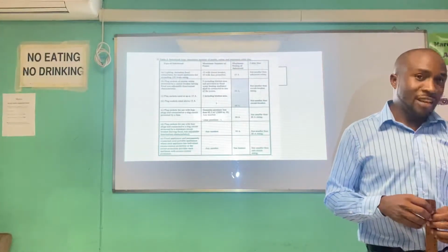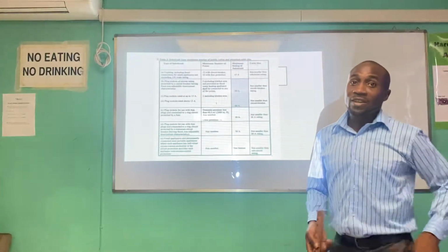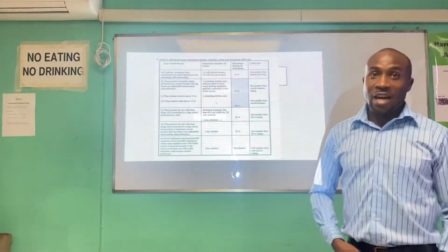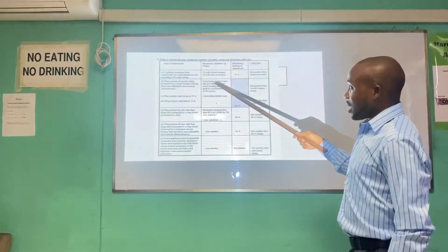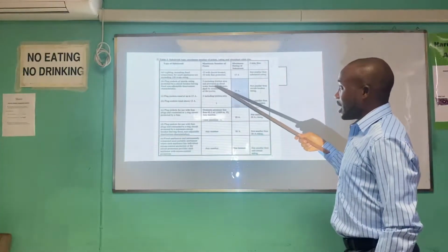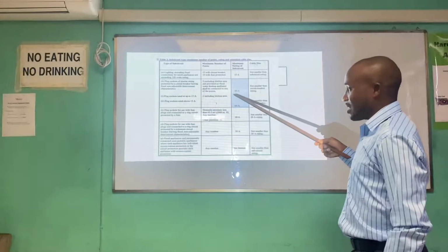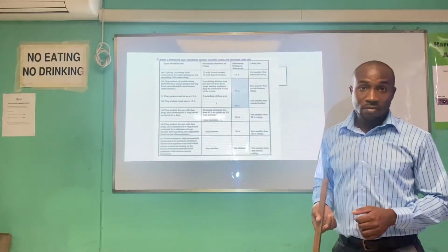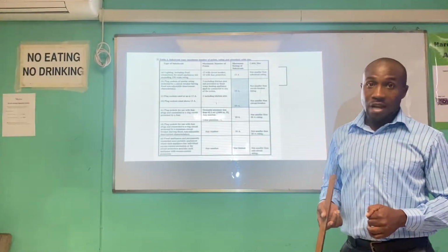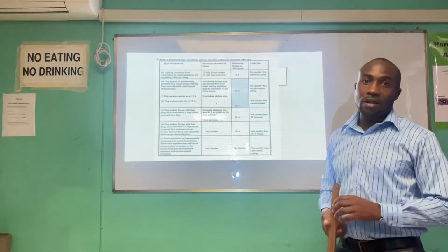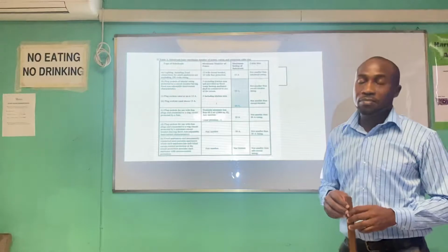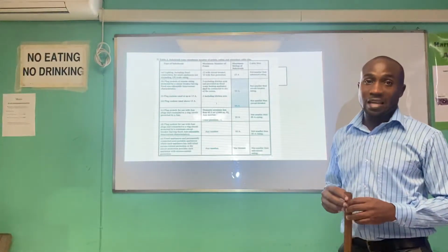Equipment, yes: fridge or microwave, toaster oven and so on. So you want to ensure that you have a particular circuit assigned for that equipment, and not mix your microwave circuit with your fridge and so on, because you're going to have breaker tripping quite frequently in that case.